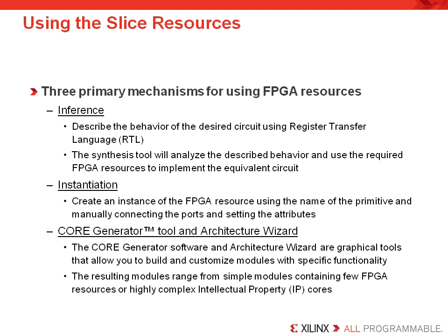Xilinx provides a library of primitives called the Xilinx Unified Library to all of our synthesis partners, as well as to our customers, so they can create netlists that are optimal for their customers. While this same library is available to you anytime you want to instantiate a primitive into your FPGA.